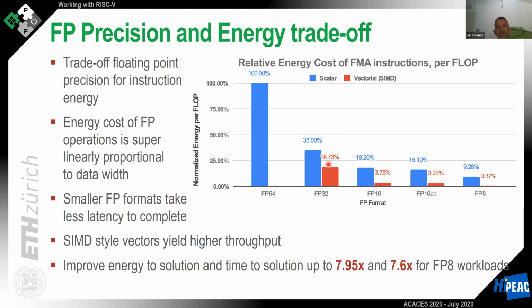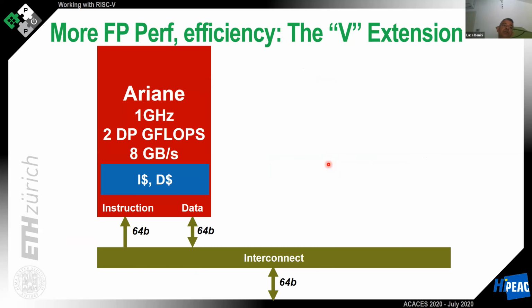So if you go with a larger floating point unit, your cost in terms of number of gates increases superlinearly. So you have a joint energy advantage due to the fact that you run in a shorter number of clock cycles. Remember, energy is power multiplied by time. And also the fact that you run SIMD, and finally the fact that you have a much superlinearly simpler design. So again, SIMD is a very good idea to recover your energy efficiency, especially if you work with floating point numbers. But actually, this is not enough.